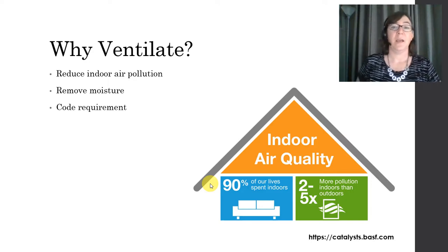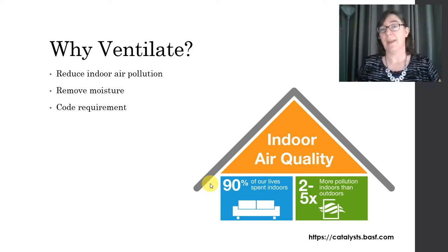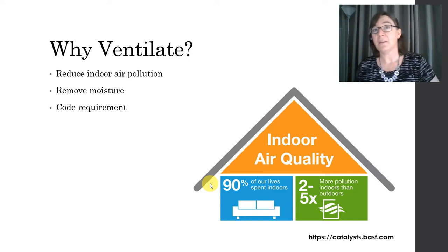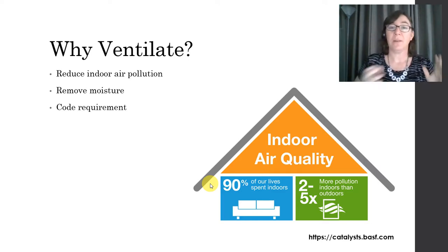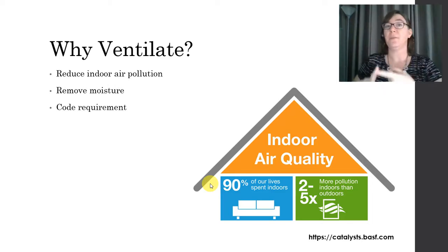Why do we need to ventilate? Well, it turns out that in our society and in our culture, about 90% of our lives are spent indoors. And surprising as it may seem, there is between 2 and 5 times more pollution indoors than outdoors. So, why do we need to ventilate? To reduce indoor air pollution, to remove moisture, and also because it's code required.